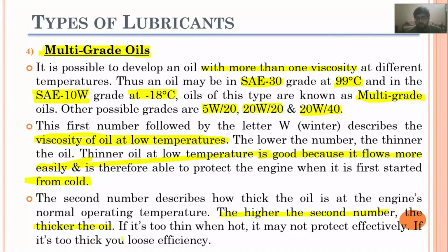If it's too thick, you may lose efficiency as well, or it may provide resistance against the moving component. So what the car manufacturers do is they provide you the grade for that lubrication oil, or if you are purchasing some IC engine for power generation purposes, they provide the grade of the lubrication oil which you will use in your IC engine.